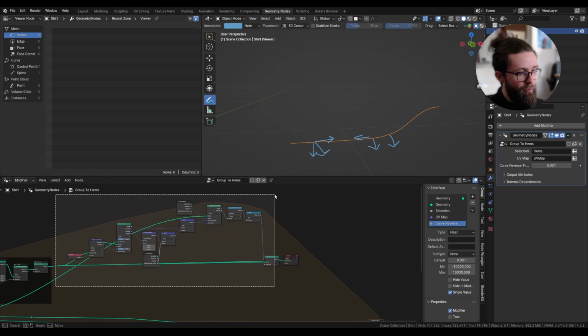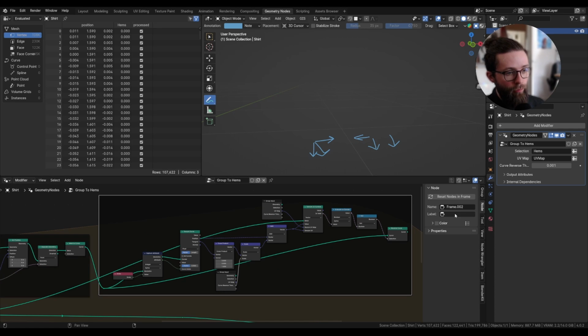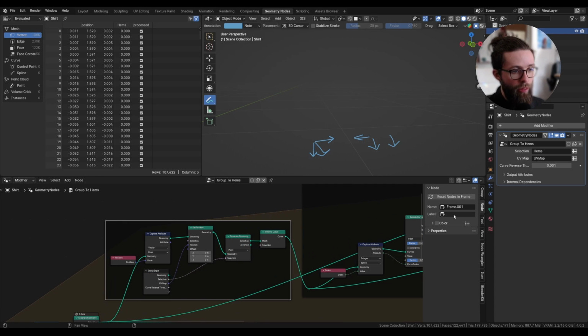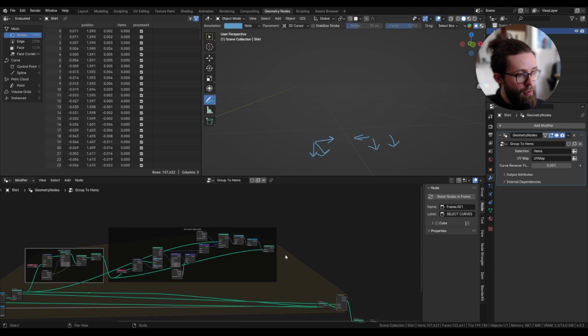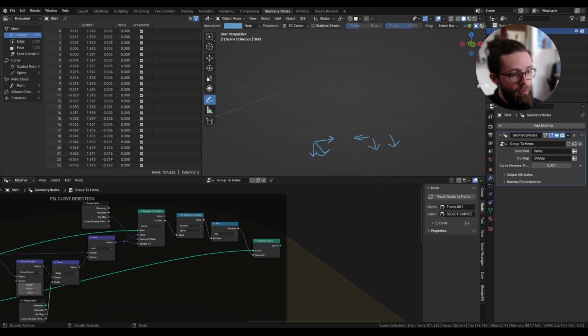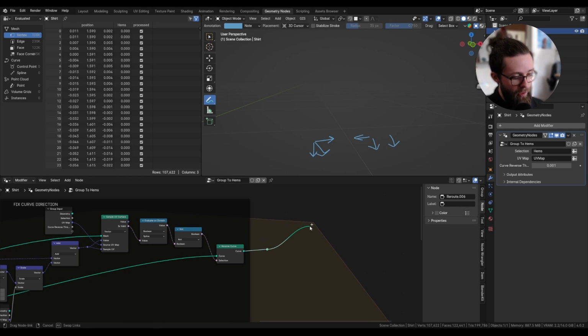Now we can also frame this, because this is another processing step, which we can label fix curve direction. And the block from before was just select curves. Now on this curve we need to do a third step of processing, which is to compute a bunch of attributes. So first we need to separate two cases. In the first one, our mesh will still be in the UV space, and on the second one we want to move it back to its original space.